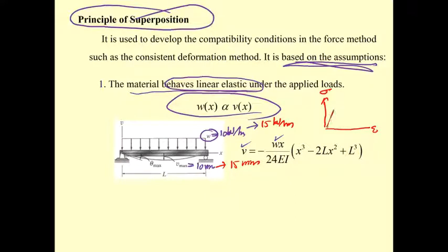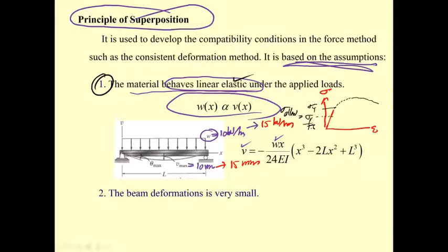Okay, and what it means is under the application of this force, what we consider is only this portion of the behavior. Okay, we didn't consider this portion, and if this one is sigma sub y, we also use this one as the sigma sub y divided by factor of safety, which we use as the sigma allowable. So usually our civil engineering structure is linear elastic, and since it's linear elastic, most of the time it's going to have very small deformation.